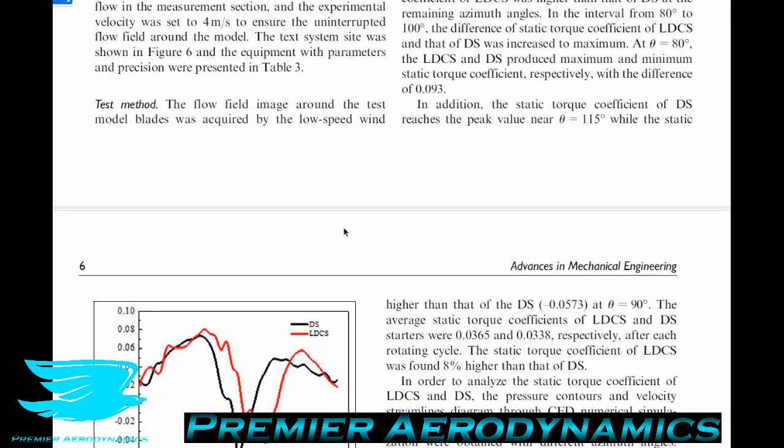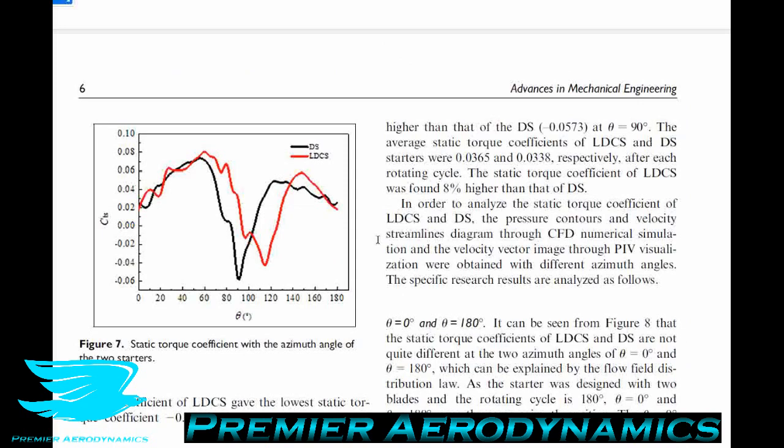The point at which the blades start to turn is when the torque produced exceeds the internal friction drag of the turbine. And the non-dimensional number is the static torque coefficient. This number will change depending on where the blades are located around the axis. For example, if one blade is located at the front of the axis and the other one at the back, the forces the blades produce will be different to if the blades were located on each side of the axis. This is simply because the geometries that the oncoming flow is seeing are different.